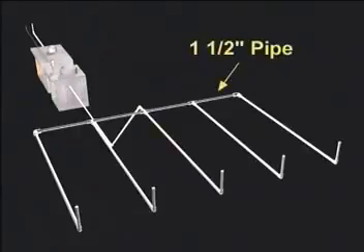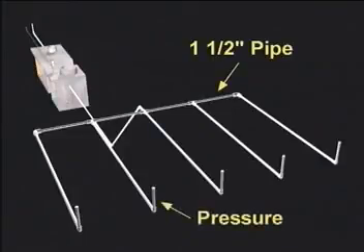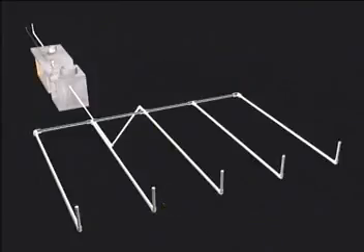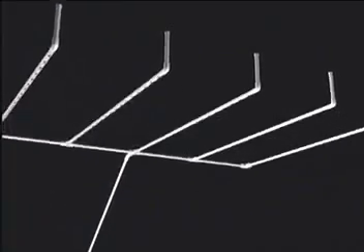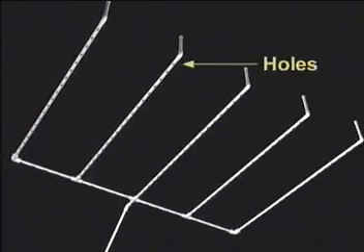In this system, we have specified 1.5-inch pipe, but keep in mind local codes may dictate pipe size. Operating head is the pressure which must be maintained in a lateral, expressed in feet of head, usually measured by an open standpipe temporarily placed at the end of a lateral and adjusted by valves in each lateral or according to your local code. Flow, expressed as gallons per minute, can be calculated by multiplying the number of holes by the flow rate corresponding to hole size and operating head.